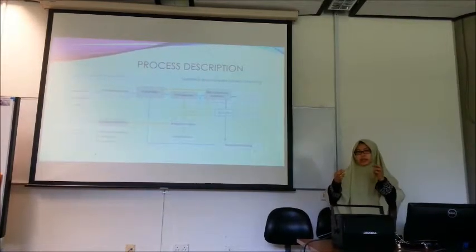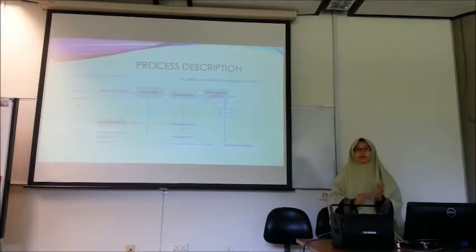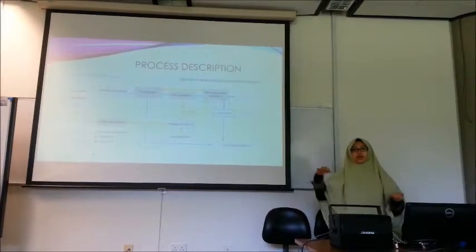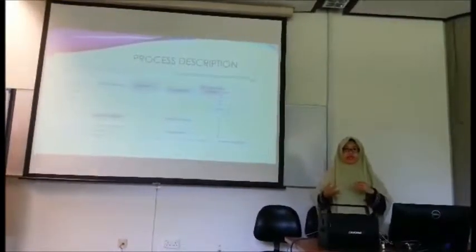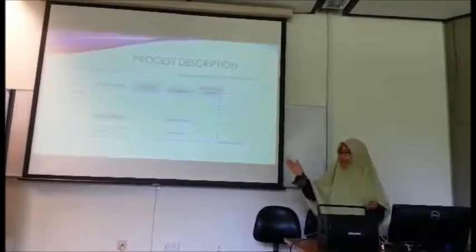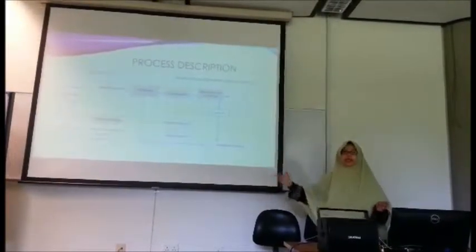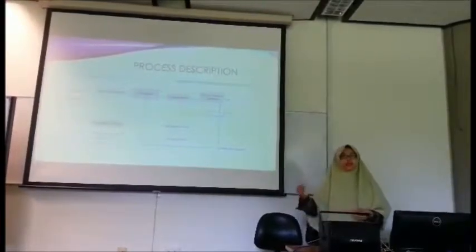The concentrated product will then go to the high concentrator. But the water left will go to a condenser. The water will be condensed in the condenser, and then it will go to biological cleaning, membrane filtration and exhaust air purifier before we can reuse it as clean water.